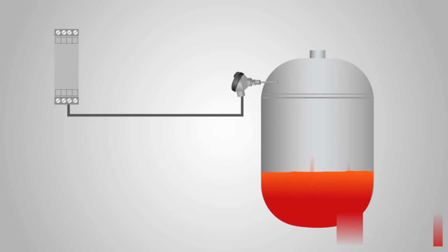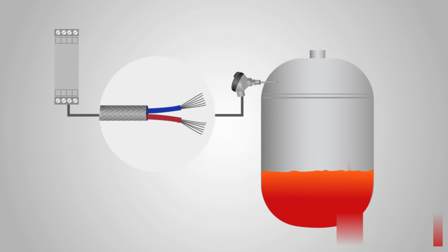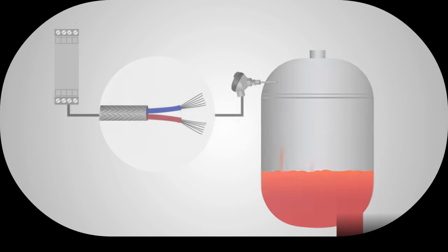Since the functionality of thermocouples is based on thermoelectric effect in different types of conductors, when the location of a thermocouple is far from the measuring instrument, for example the electronic transmitter, the proper type of conductors should be used for extension purpose. Otherwise, the tiny signal generated by the thermocouple will be added with some error at the point where the thermocouple wires are connected to the extension wire.